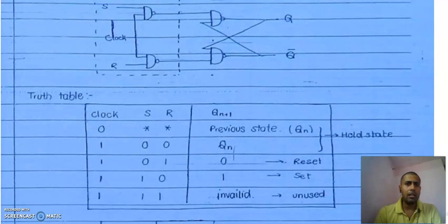So we will get output as 1 after the first NAND gate. In the SR latch using NAND gate, we have already seen that if input is 1 1, we get the previous state. That means if we don't apply the clock, output never changes in flip-flop. Flip-flop output may change only if we apply the clock. Until or unless we apply the clock, remember it, output will never change in flip-flop.